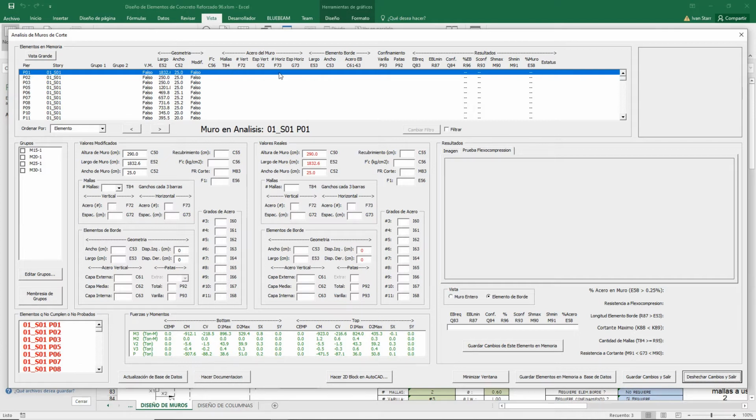And you fill in this engineering data in one of two methods, and that is manually by entering it individually here, or with engineering data groups, which will allow you to assign all the data or assign part of the data for individual shear walls at one time.